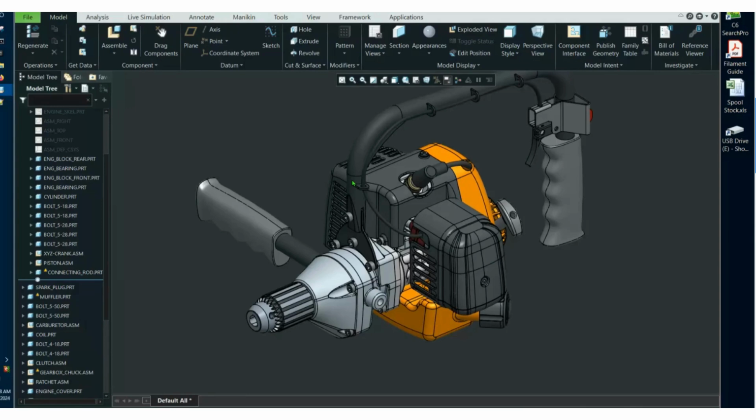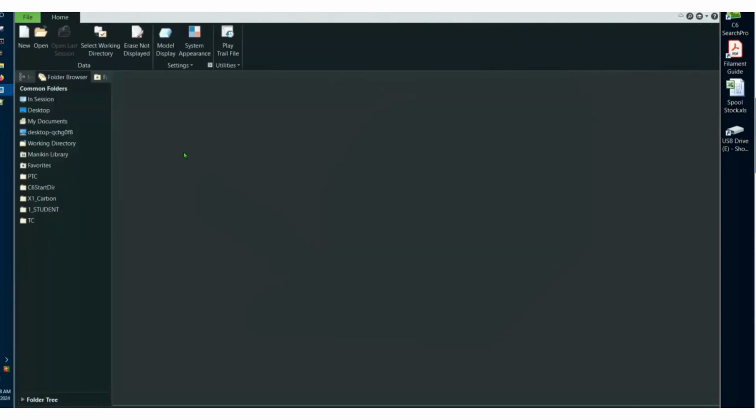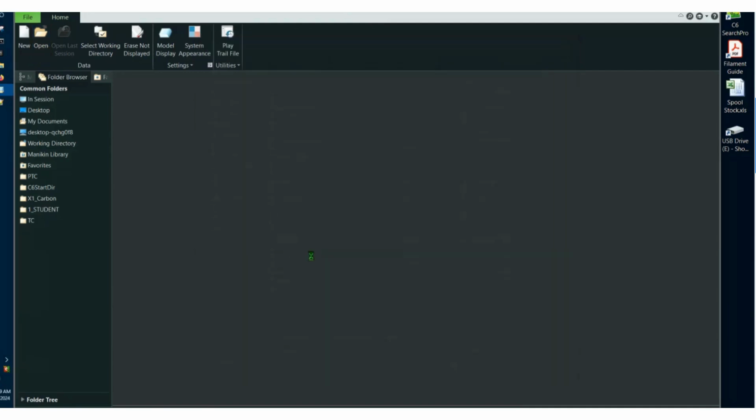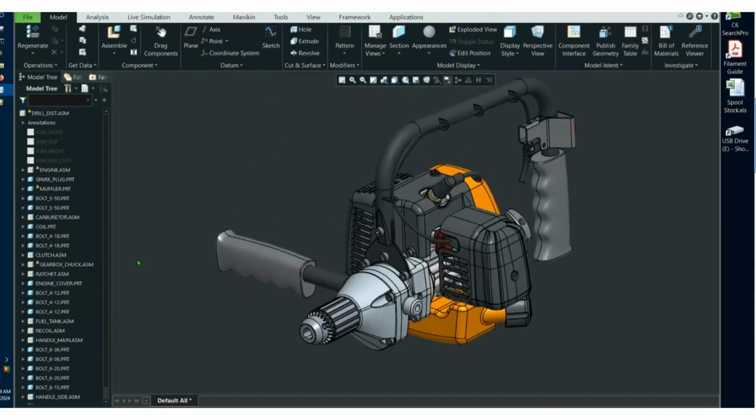So I'm going to go ahead and blow all these things out of memory here real quick. And I'll go back and put the name back as expected because I didn't save anything. And now, of course, we can go ahead and retrieve that assembly as expected, just like before, because I took the name back to what it was prior to doing that. If I had saved that assembly while it was XYZ crank, I would have effectively completed that process with XYZ crank being the new object that the assembly wanted to retrieve.